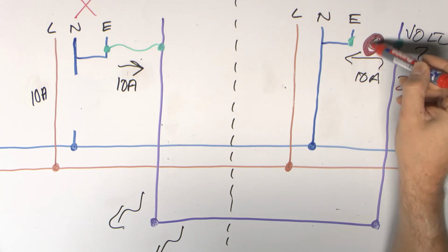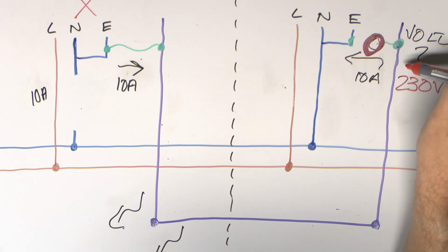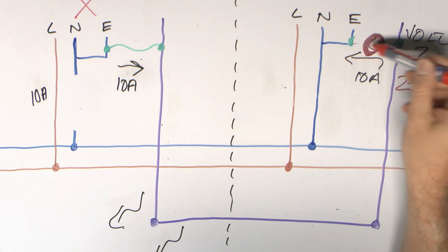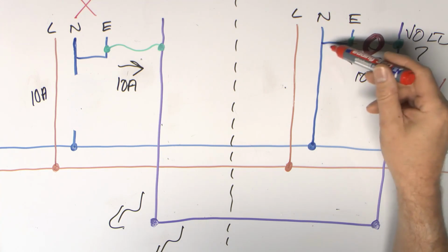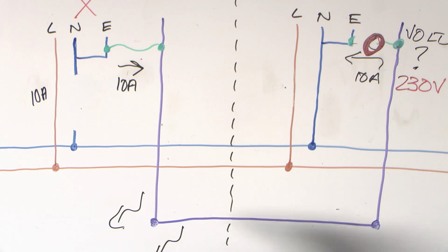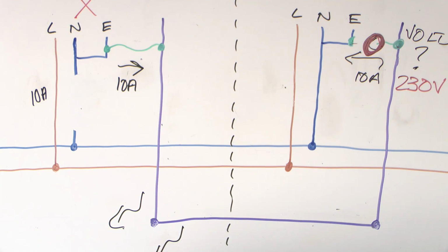However, if you were then to touch the end of this standing on the ground, you can get an electric shock from this or from the pipe itself. While it's connected, that's not a problem because again it's connected solidly through with the copper there. It's all going to be at or around the same voltage or potential. Once it's disconnected, not anymore, you're going to have a significant voltage here, say anything up to the 230 in